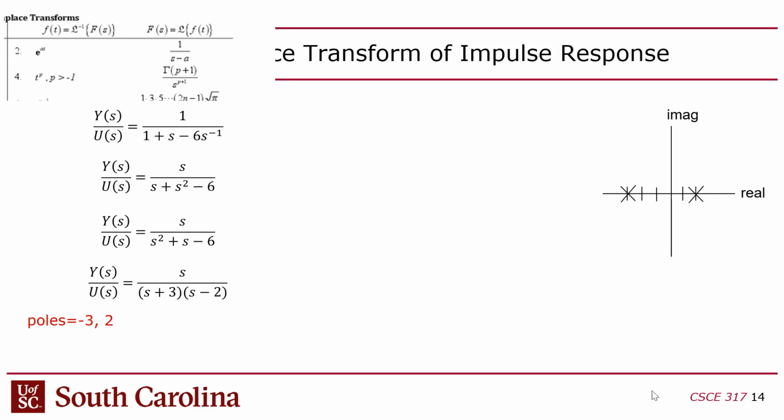So by the way, let me step back here. When I say simulate, the simulation is actually a numerical solving. So what you're doing is running an algorithm on this transfer function. Number one, it has to discretize it, so you have to basically sample at fixed points in time. And two, it's using a numerical method to figure out what the response is to this. It doesn't solve it directly.